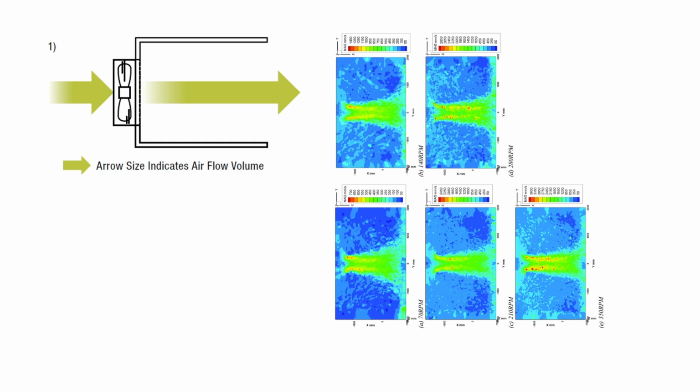If you do a CFM test like this, all the fans will most likely be in the correct order, meaning high performance to low performance, that we see in my case simulation test. But the difference between top performer and bottom performer is going to be dramatically different than what you see in the case simulation test, depending on what distance you actually care about. Effectively, this is like taking the airspeed at more or less point blank from the fan. So the case simulation test, I think, is actually golden, and it's the way that everybody should be doing case testing.